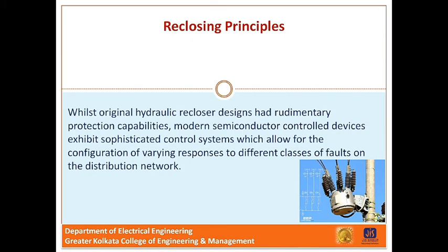Sensitive arc fault protection in recloser is typically set to immediate lockout. This detection of small leakage current less than 1 ampere on a medium voltage line can indicate insulator failure, broken cables or lines coming into contact with trees. There is no merit in applying reclosing to this scenario, and the industry best practice is to not reclose on sensitive arc fault.